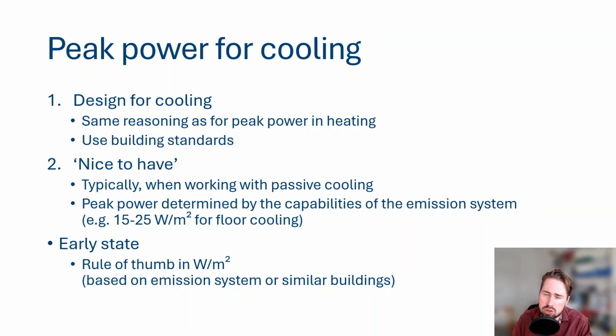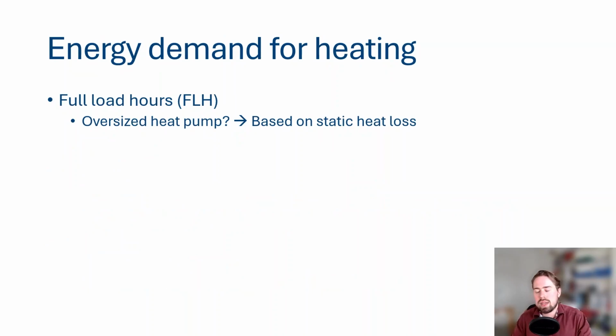Now, the other side of the story is not the peak power, but the energy demand. And there are, again, a couple of ways to calculate this. The first one is using full load hours. So what we do here is we say, well, imagine we have a heat pump of 10 kilowatts, and we say it has 1,000 full load hours. Then we know that it requires 10,000 kilowatt hours on a yearly level.